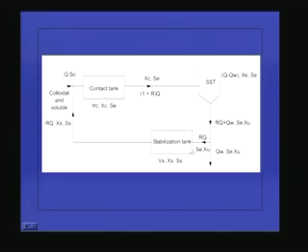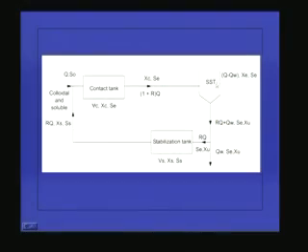Here, the difference from the conventional plant is that in the contact tank we give a very short detention time, maybe 30 minutes. So whatever soluble BOD is highly degradable will get degraded, and some biomass increase will take place. And for the colloidal particles, we give enough time here so that they get attached to the microbial cells. So we will have biomass with colloidal particles attached to it, and that will come to the secondary sedimentation tank.